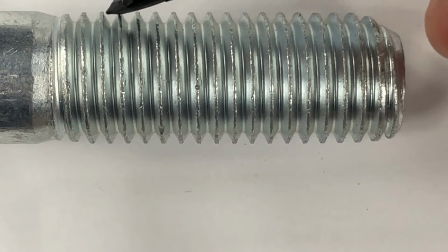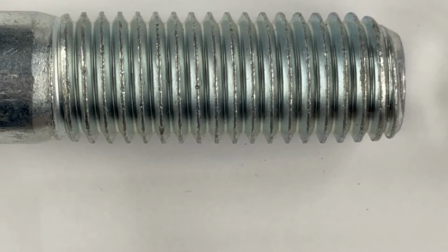what you'd see is a 60-degree thread profile. So the different profiles are unified national coarse threads, and there's metric, SI metric threads. There's special 60-degree threads that maybe you'd see in a micrometer. And then we have Acme, buttress, and Brown & Sharpe threads, which are kind of square shaped. And then we have our pipe threads. So those are all the different types of thread forms or thread profiles.